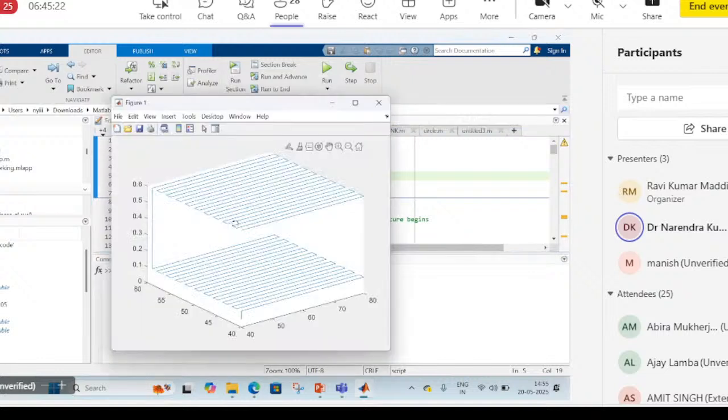The first layer toolpath has been generated at a standoff distance of 0.1 mm from the base. However, the second layer has been generated at 0.6, which means the distance between these two is 0.5 mm. The base layer will be printed with the standard distance of 0.1 mm.